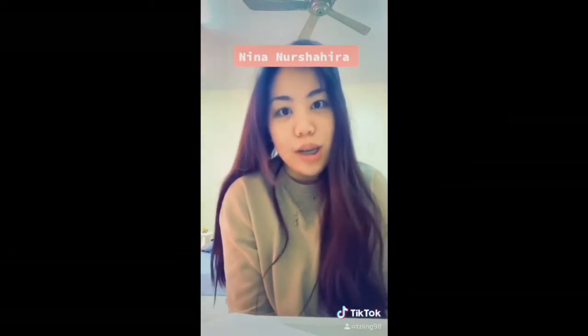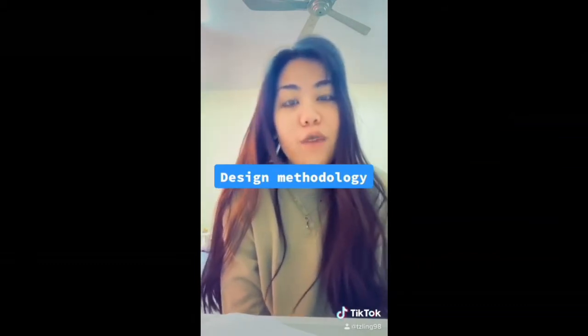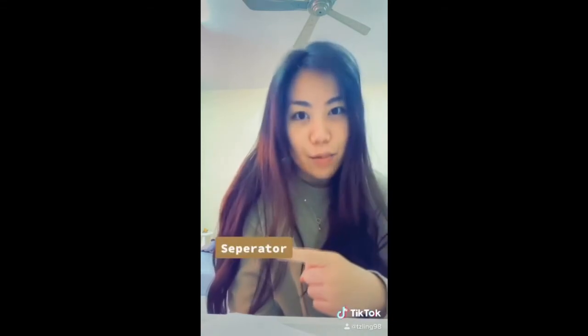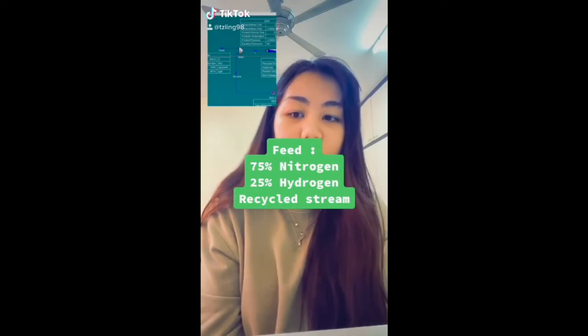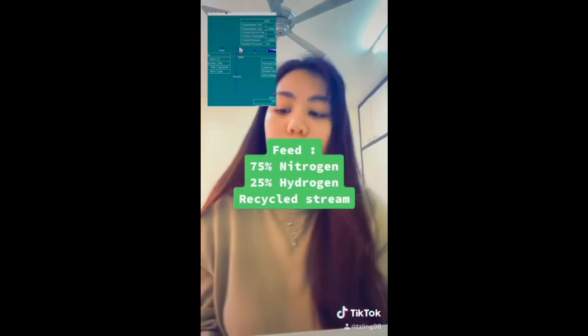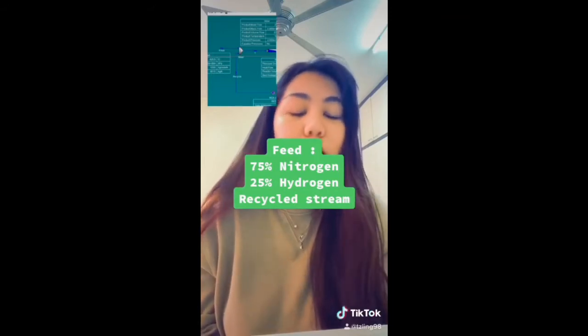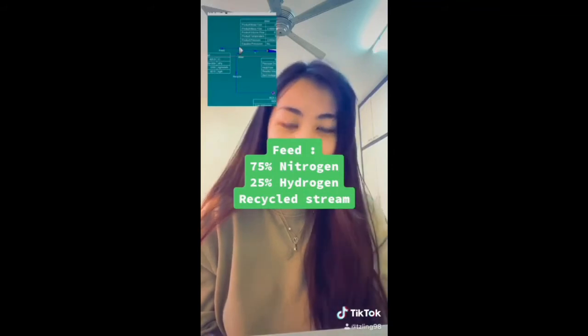Hi guys, my name is Nina Nur Shahira and I'm here to present the design methodology of our process. We have four unit operations in total: a mixer, a reactor, a heat exchanger, and a separator. Now let's talk about the mixer. We have 75% nitrogen and 25% hydrogen going in as the feed, and we also have the recycle stream from the separator at the end of the process.